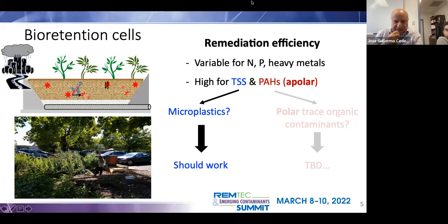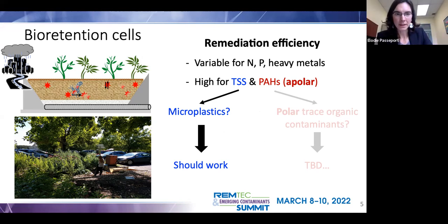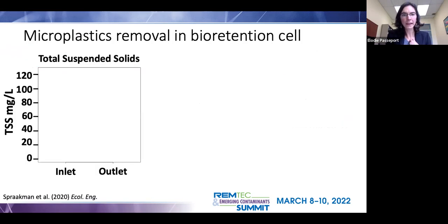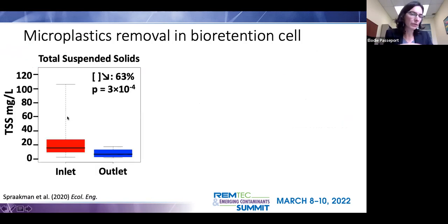Yes. Okay, so the answer is yes for microplastics. We've worked on bioretention. This bioretention cell, we've studied it quite widely, and we found, which is also found in the literature, that it works very well for total suspended solid removal. Obviously, it's a physical filtration problem, so that's why it works very well. The particles are just stored in the system. That led us to hypothesize that microplastics could also be removed in this kind of system. And indeed, as I show here, one of our first papers by Sylvie Brackman showed that there is a significant reduction in concentration of total suspended solids between the inlet and outlet of this bioretention cell.